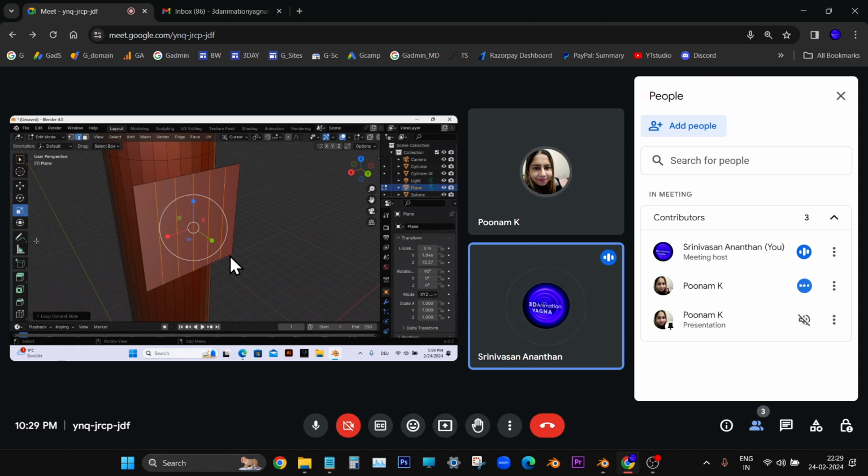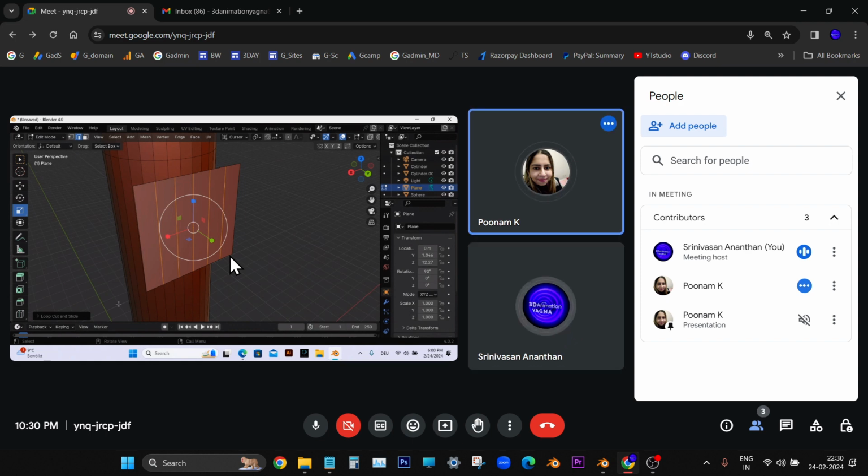So without deselecting this, you can minimize it. Otherwise, generally what they do to make this dialog box disappear is click outside. What will happen is the edges will get deselected, and they have to rework and select them again. To avoid that rework, I'm telling you this.